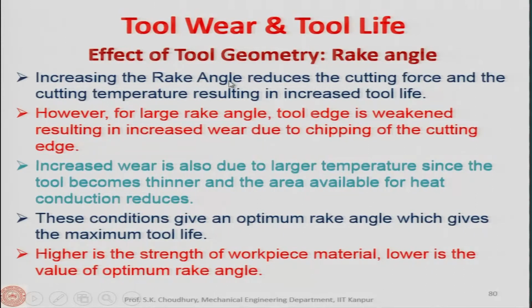So, what we are saying is that we increase the rake angle as far as possible, because increasing the rake angle ultimately increases the tool life by decreasing the cutting force and decreasing the temperature occurring during the machining process. That is one thing. And the reason, I have already told you what is the physics behind it, that is what happens to the shear plane as the rake angle is changed. The shear plane is changing, and because of that, as the rake angle is increasing, the length of the shear plane is decreasing.